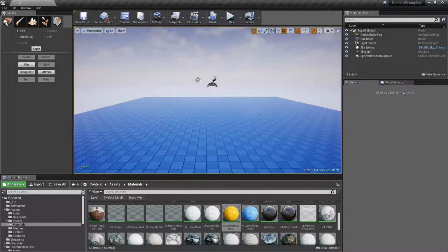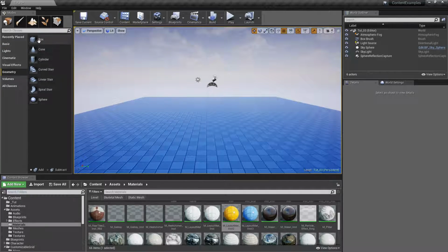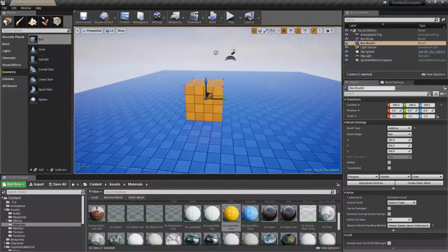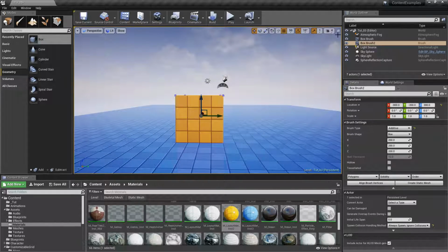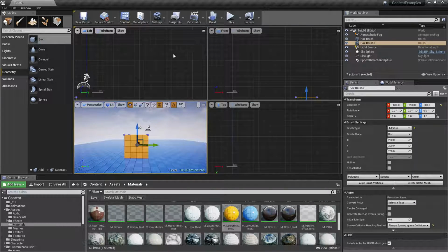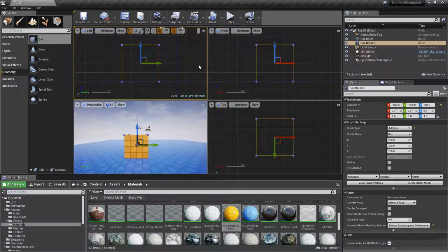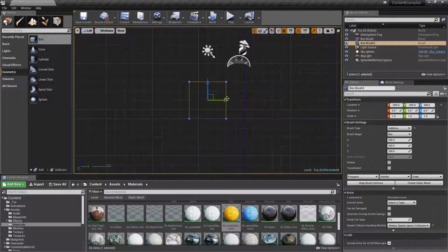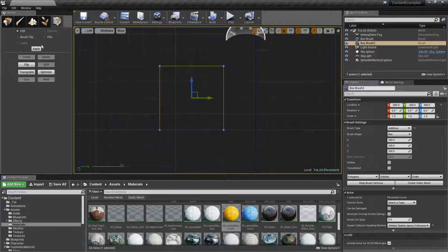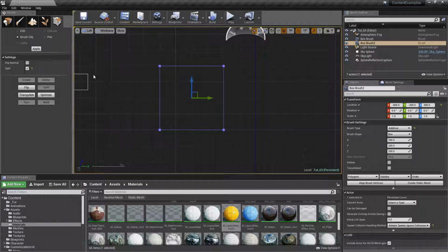Let's get brush clip. For brush clip, I'm going to make a new brush and go into, doesn't matter which view, to be honest, for demonstration purposes. Into brush clip. Brush clip cuts your brush. So you can either split it, flip normals, or cut it. It matters from which side you start drawing.